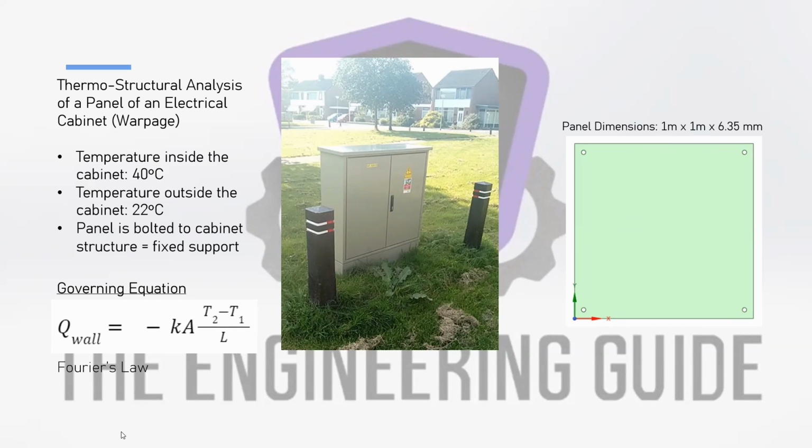So there are multiple ways that I could view this situation. One of the ways would be that I dimension a panel to be 1 meter by 1 meter by 6.35 millimeters, which is equal to a quarter inch. And we could say that the temperature on the inside of the cabinet maintains the inner wall of this panel to be 40 degrees Celsius, and the ambient temperature around the cabinet maintains the outer wall of the panel to be 22 degrees Celsius. Evidently, this is going to cause thermal conduction through the plate.